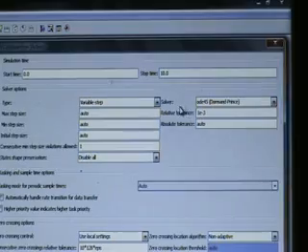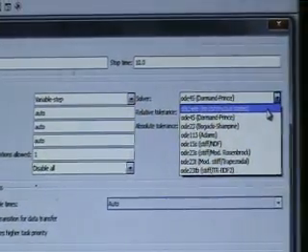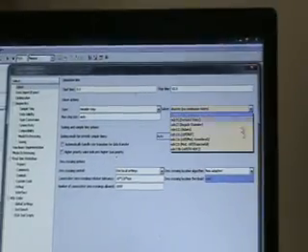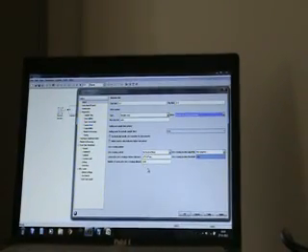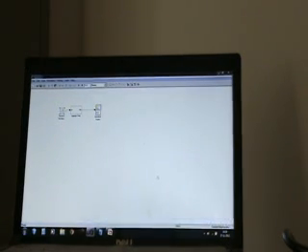So we have a block named solver, which is used to change the input into discrete. Once it is changed to discrete, the other parameters are the default parameters and they get auto adjusted. After this we click apply and then OK.